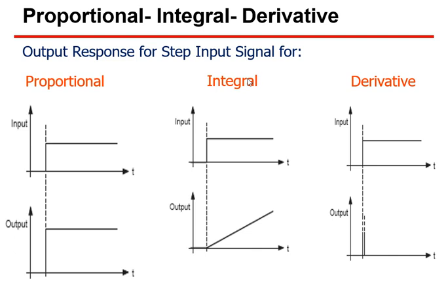When the system is integral and we apply a step input, we will get a continuously increasing slope, a graph like this. I think you have studied, or you may study in future, that whenever a square wave is applied to an integrator electronic circuit, it converts the square wave into a triangular wave. That is the reason, because it gives you a continuous slope like this.